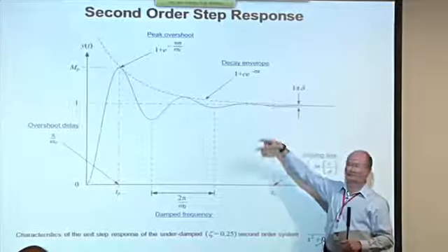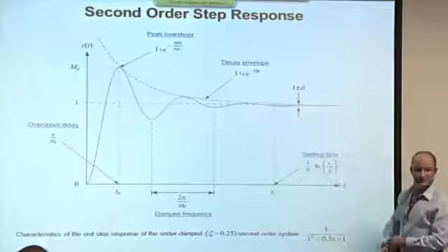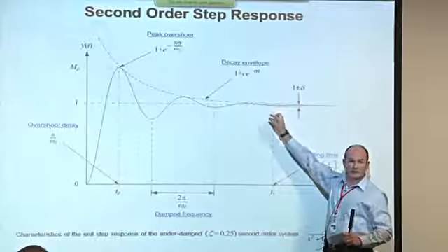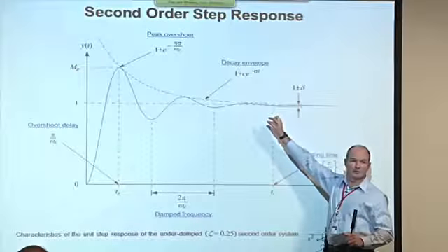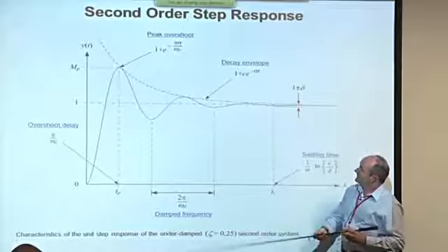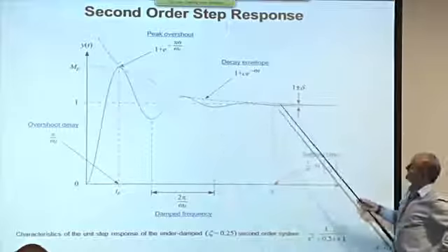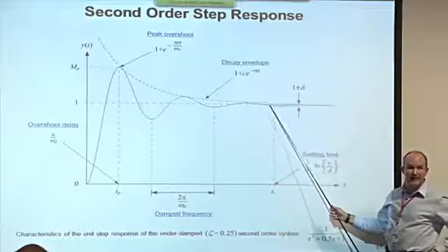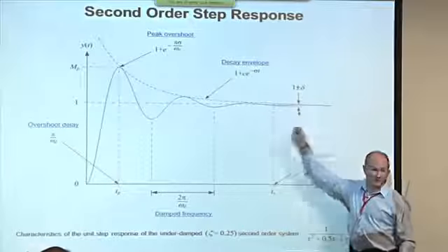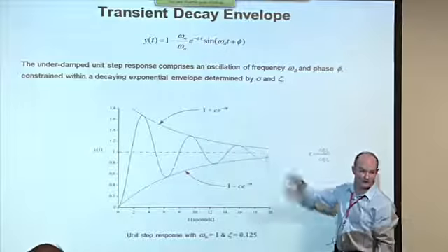Now, obviously, in a transient response which has oscillation like this, the time response is going to go whizzing through that several times before it settles permanently within there. Now, the last time at which that happens is very difficult to compute analytically in terms of parameters. So what we do is we take the settling time as the time it takes the exponential decay envelope to intersect with the error band. And then you know, whatever the oscillations are doing, they're never going to go outside the error band because they're constrained by this exponential envelope. So you look at the time that it takes to get there.